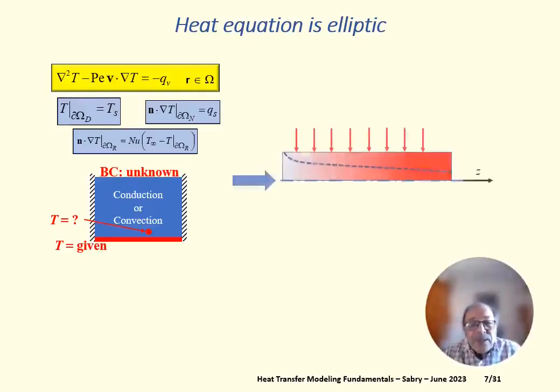Let us reconsider this fact for a convection problem. We have fluid flowing in a duct and heated by the walls. The dotted line represents the evolution of the thermal boundary layer. Now, because the problem is linear, if it's a forced convection, then the velocity is known, and then the energy equation will be an equation in the temperature only, which will be linear, as you can see.